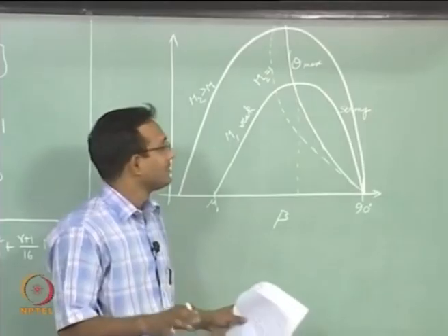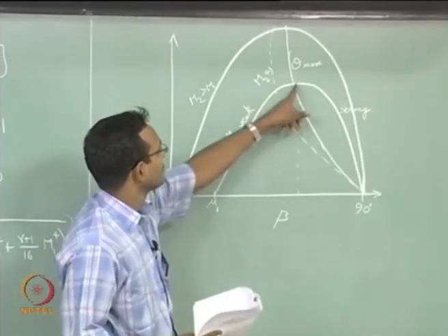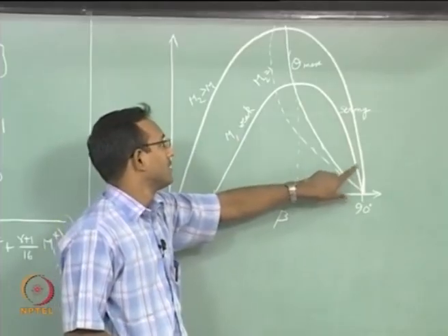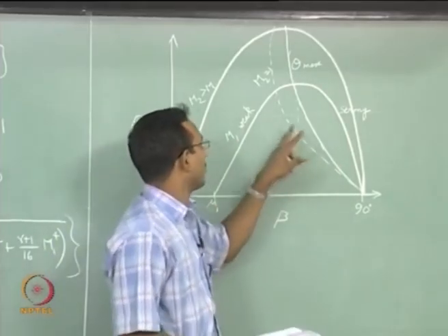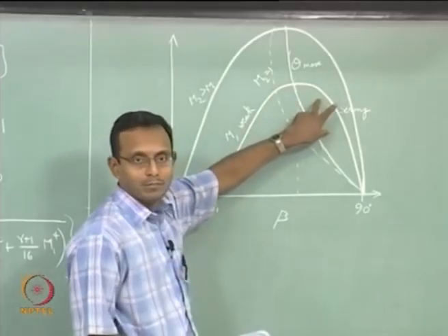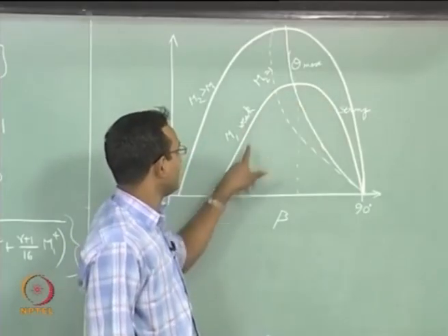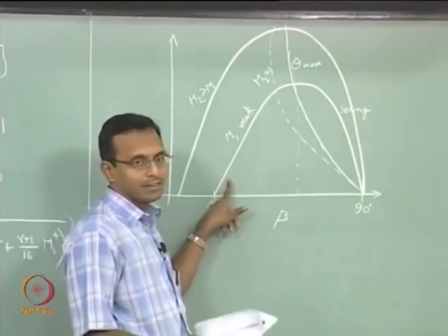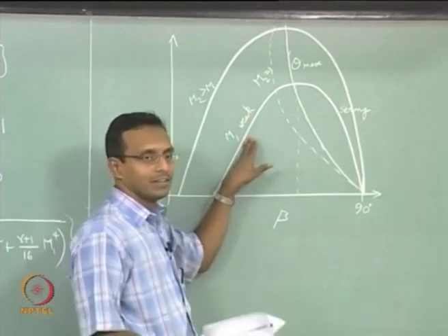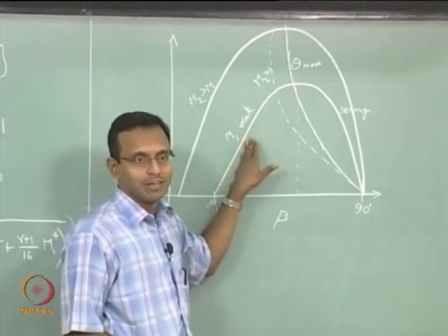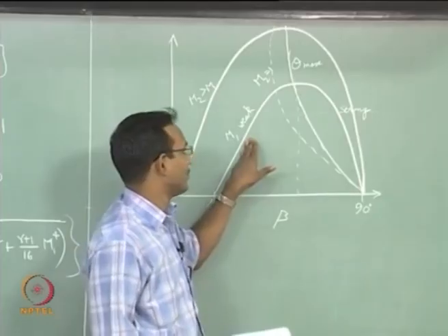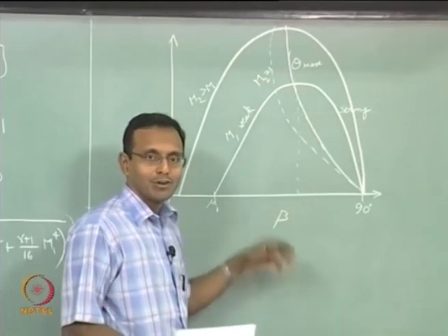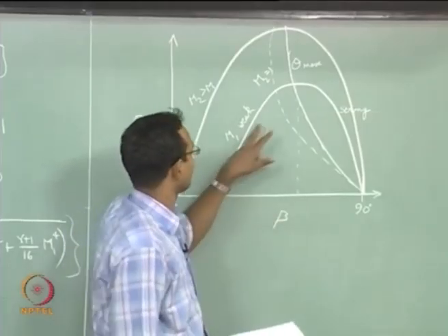What you have to note is, if I think about a strong oblique shock, then I am going to have only a subsonic condition behind the shock. If it is weak, for low values of theta, I will have supersonic flow behind the weak shock solution. Why do I call it a solution suddenly? It is the solution to our equations and it gives two answers. So, I call one of them the weak solution, the other the strong solution. Okay.